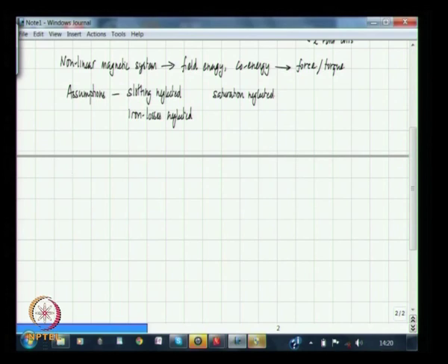What we did was we transformed to the stationary reference frame. So the requirement was that if the inductance description is not to change with respect to rotor angle, it can only happen if all the 4 inductances associated with the 4 windings that we are considering in the system should all be stationary with respect to each other.